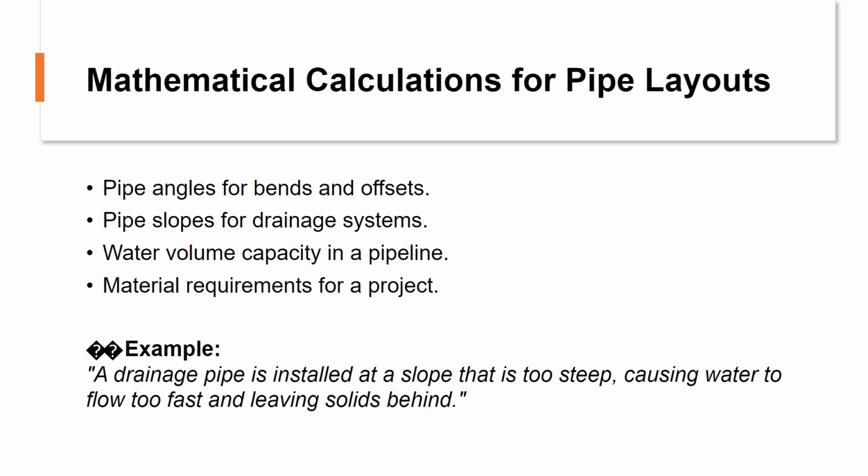Material estimation. Before you start a job, you should already know how many metres of pipe you need, how many bends, elbows, and tees, and how much slope you'll build in. This comes from careful measurements and applying the right math.